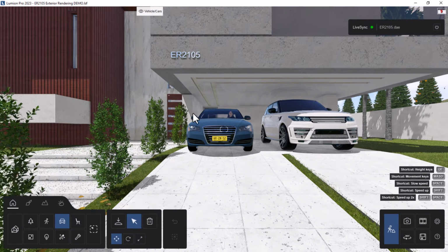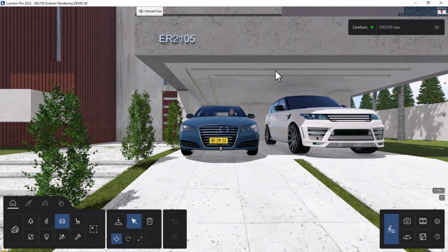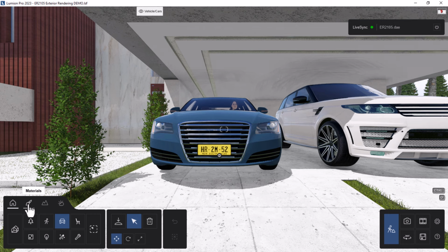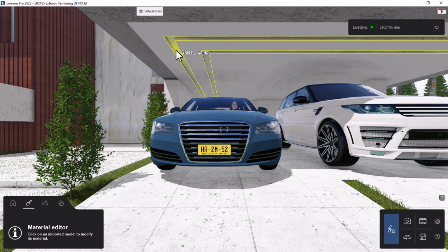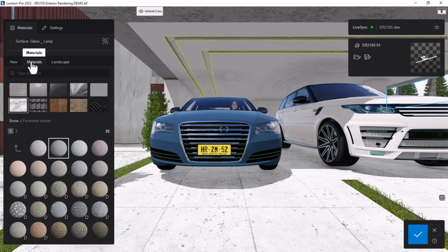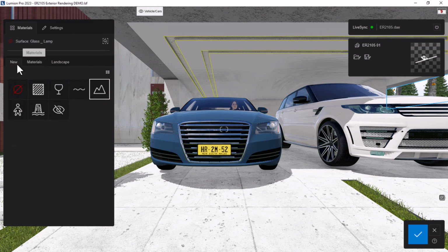What I mean by that is because I have this lighting script you have made out of a surface. So I'm going to go here under surfaces or materials, then select that. Okay, from there I'm going to apply a material. Here under new, we used to have a light map here. I think ArchiCAD decided to remove it. It wasn't really working quite well. That's the reason why they've removed it.